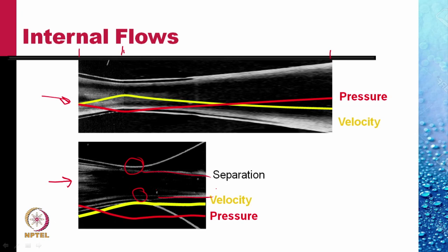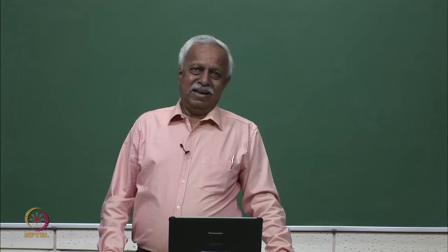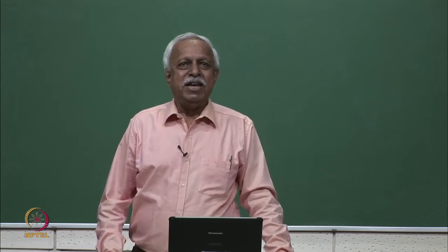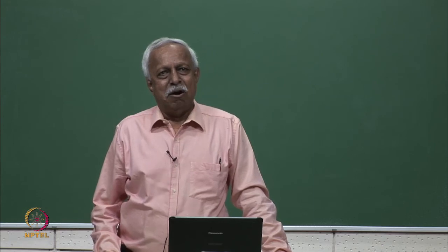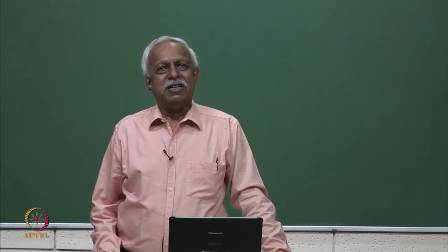And because of this, the pressure does not recover. Pressure does not increase. And so there is a decrease in pressure down this short nozzle. And this results in loss of energy. We have to be very careful about the diverging portions because the flow tends to separate.